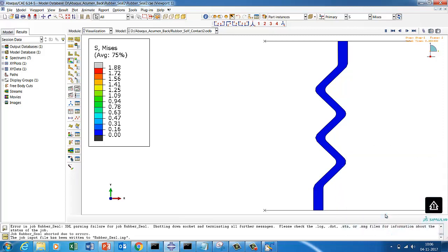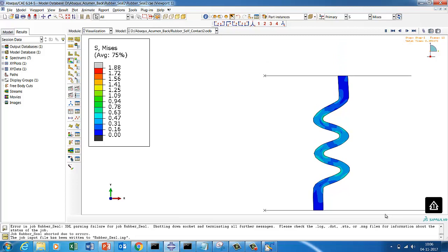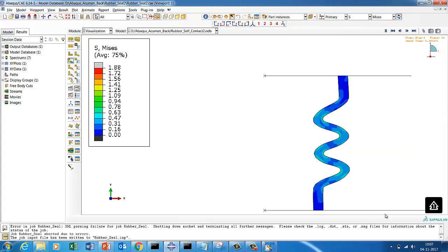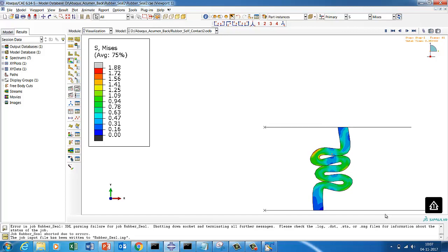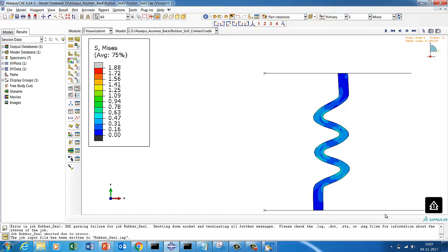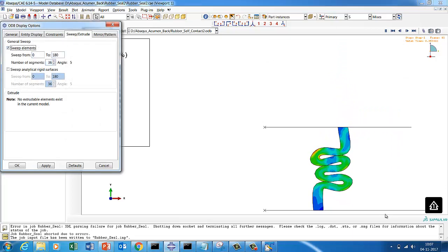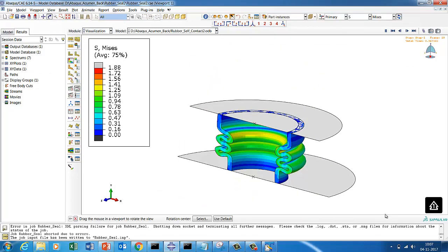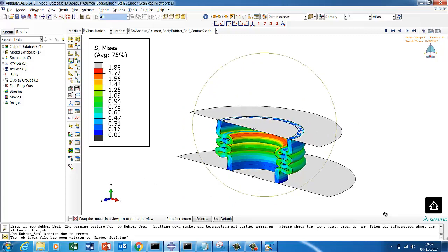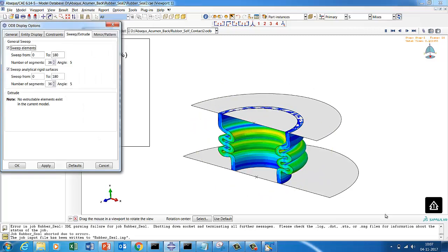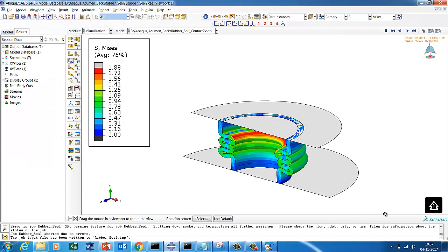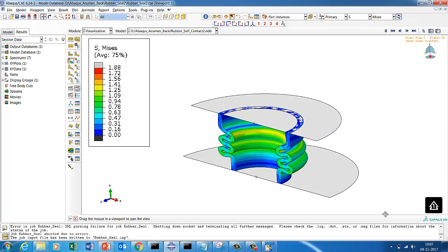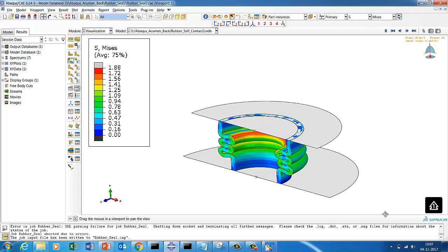So results are out. So I'm just looking at how it looks. This result is now axisymmetric. You can see there is no self contact, and then slowly it comes down, it creates self contact, and we'll just plot it. We'll sweep this by 180, so we'll have a better view. You can do this type of analysis using axisymmetry, but when you present, you just take advantage of this sweep, and then show it, so people will see it's 3D, and then you see the self contact happening. There is a tie.